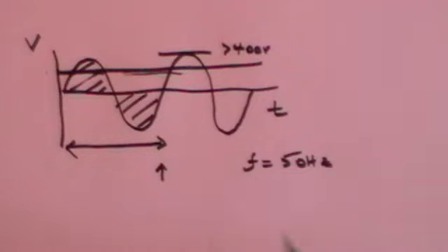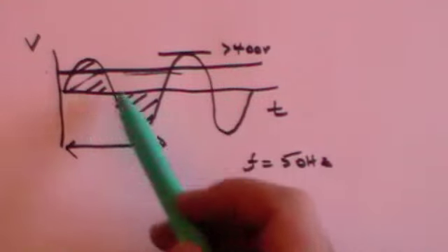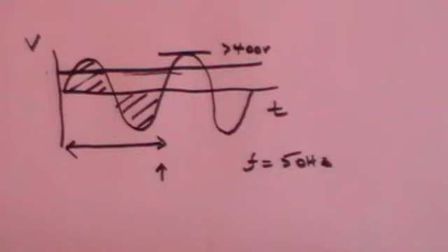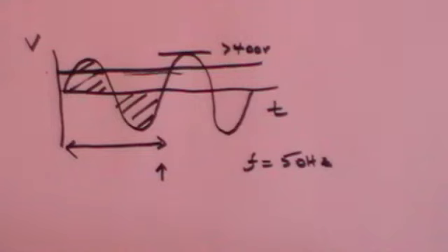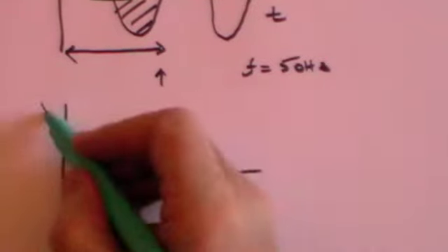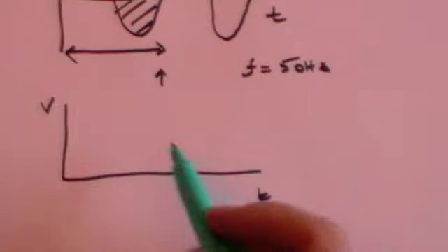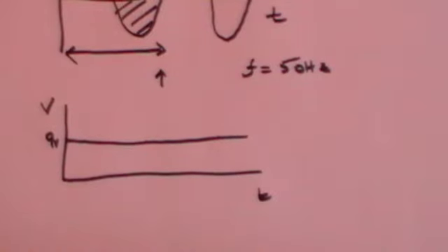But of course you only get over 400 volts for a small fraction of each cycle. So the kind of weighted average you get, which is just the accumulation of all of this, comes to 230 volts. If you contrast that with, say, a 9-volt battery, and we were to plot voltage against time, then the 9-volt battery would simply produce 9 volts until such time as the battery ran out of power. There is no variation, it's just a straight 9 volts.